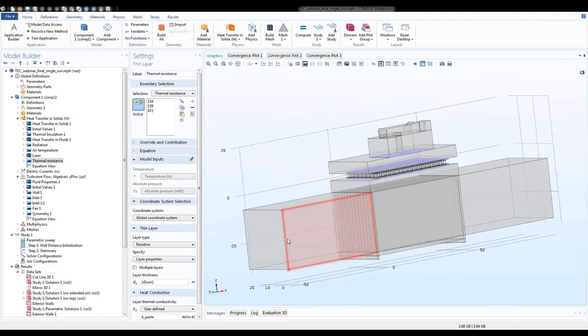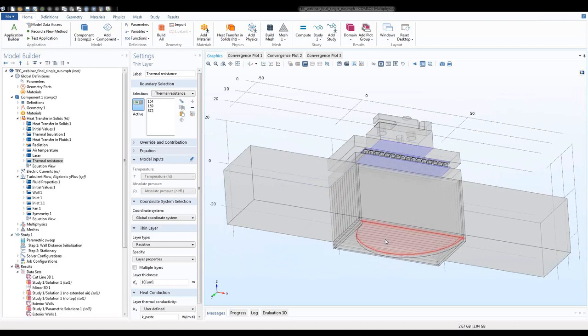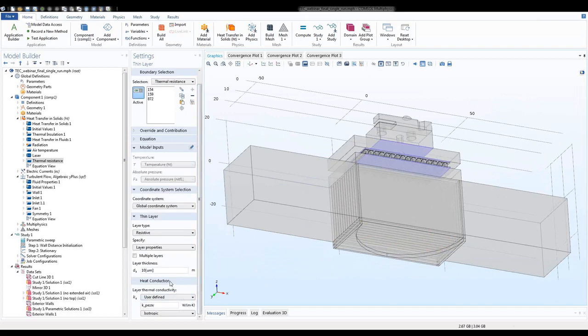As we now compute airflow, we added a turbulent flow algebraic y+ interface. The air inlets are set at the outer boundary again, where the fixed temperature boundary condition was set earlier. The air is exhausted from the circular opening where the electric fan was modeled, and the fan is modeled with a linear static pressure.